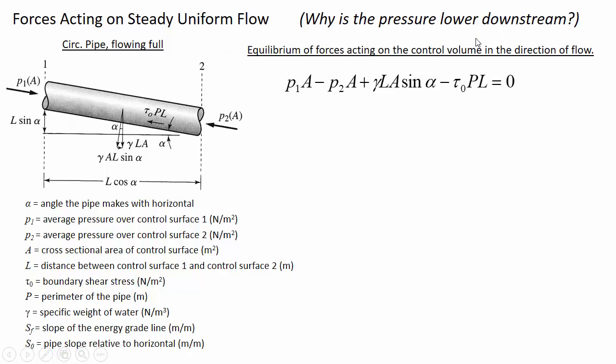Like if we were going to go one step beyond just the knee-jerk response of saying the pressure is lower downstream because of pipe friction. If somebody said, well, tell me more about that. Tell me more about the pipe friction. Well, then what you'd say is it's shear stress that's acting over the area of the liquid element. And so it's not the cross-sectional area, it's the surface area. And so perimeter is the circumference of the pipe. So it's the outside length multiplied by the length L. So L is the distance between 1 and 2.